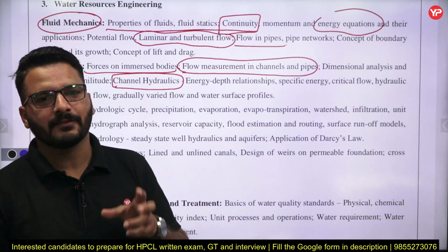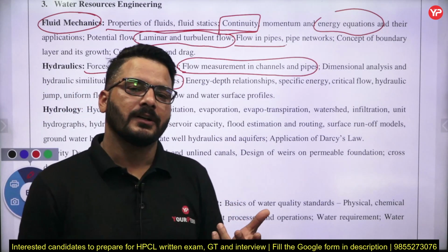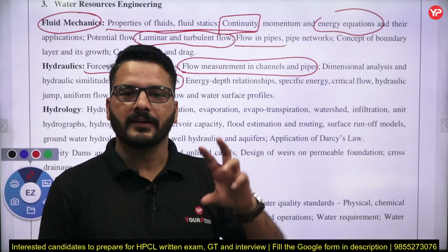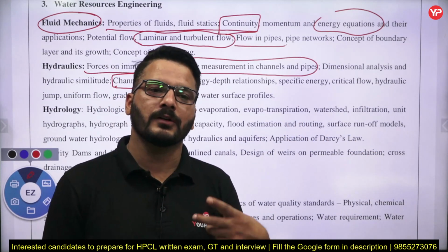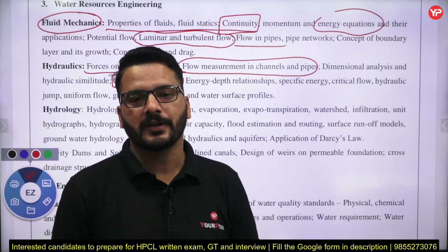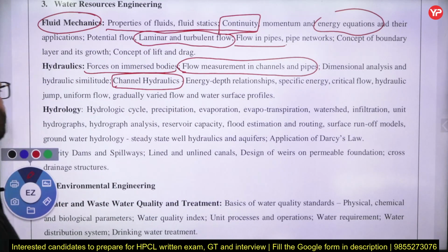So how to calculate the specific energy, what is the meaning of this minimum specific energy, okay. And regarding the minimum specific energy, is the discharge maximum or minimum, is the depth critical or subcritical or supercritical, that you have to take care of, fine.